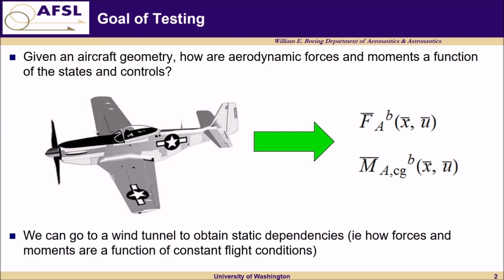For example, you might be able to temporarily get an increase in lift if you perform a dynamic pitch nose-up maneuver. However, most wind tunnels are set up to hold the model of the aircraft steady and then acquire data. So attempting to characterize dynamic aerodynamic forces and moments is typically not practical in a wind tunnel.